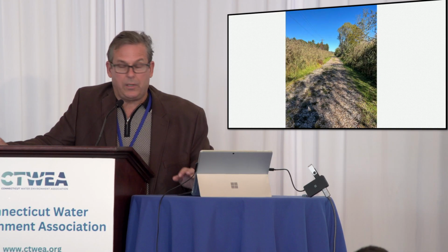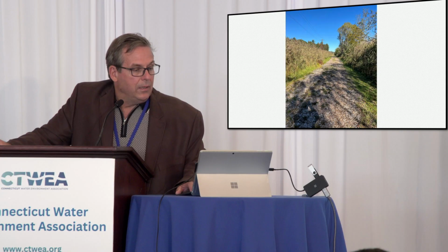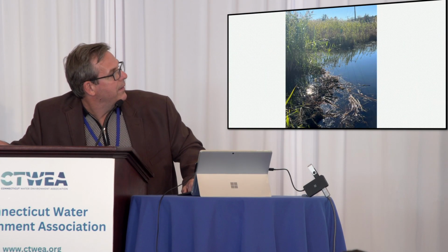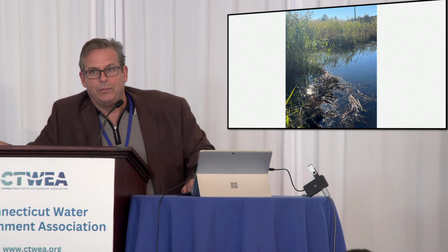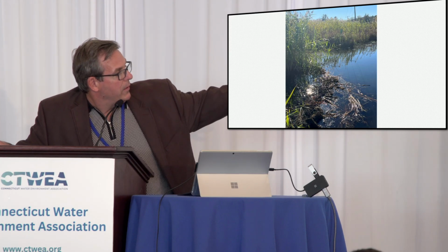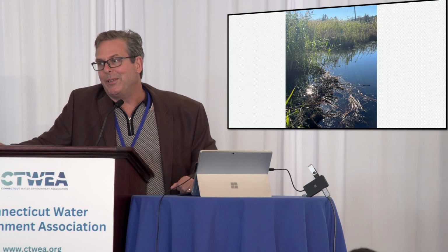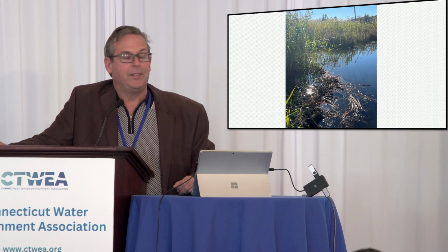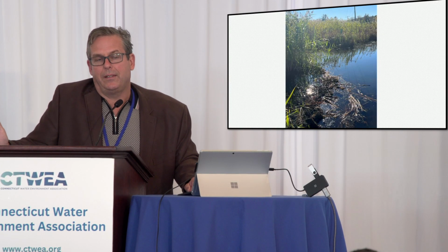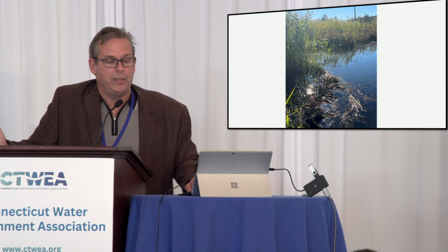So that's where we started using the Pro Rings and the watertight manholes. And this shows you, you can't see, but see that little marker right there? That's one of my interceptor manholes. And you can see the water line, how high it gets. But we have an agreement with White Woods that if we need to destroy the beaver dam, we can go there with a backhoe and do it. But they'll just rebuild. So if you have issues with beavers, there are different types of products out there that could trick the beavers so the water level won't get as high or encroach on your sewer line.